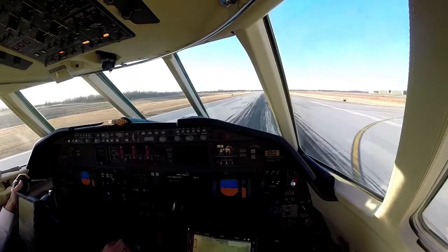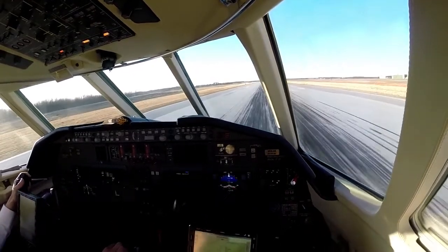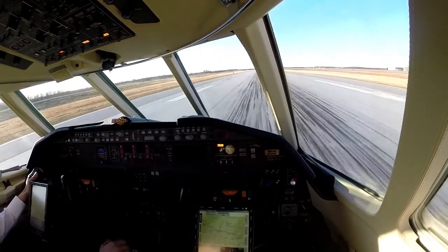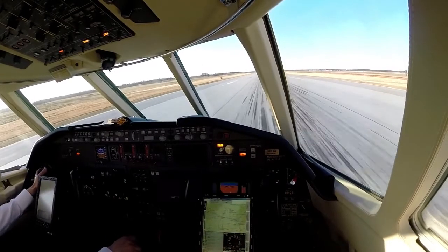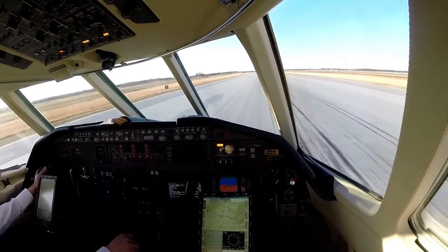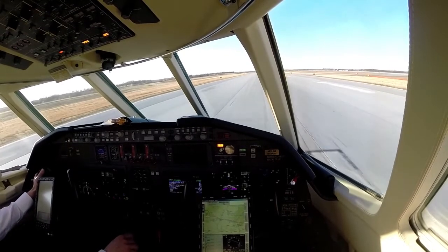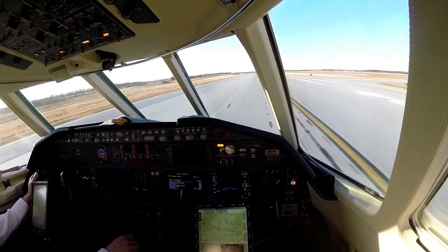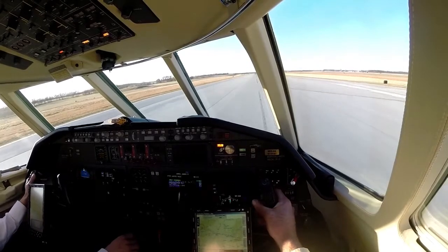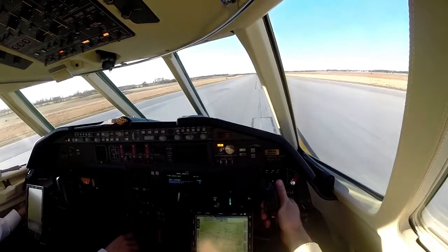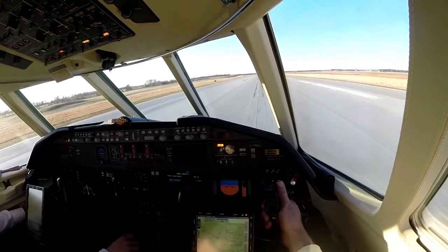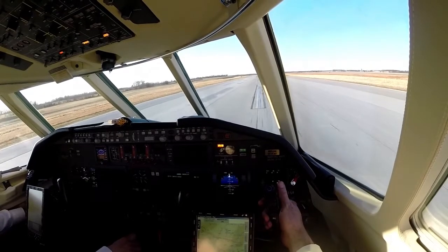If no declared distance is published, simply use the runway pavement length for takeoff planning. If declared distances are published, you'll likely want to use the more conservative of the TORA or ASDA. As the Runway Safety Area program nears completion in 2015, you can expect to see more airports publishing declared distances and more discussion about their use in everyday flying.